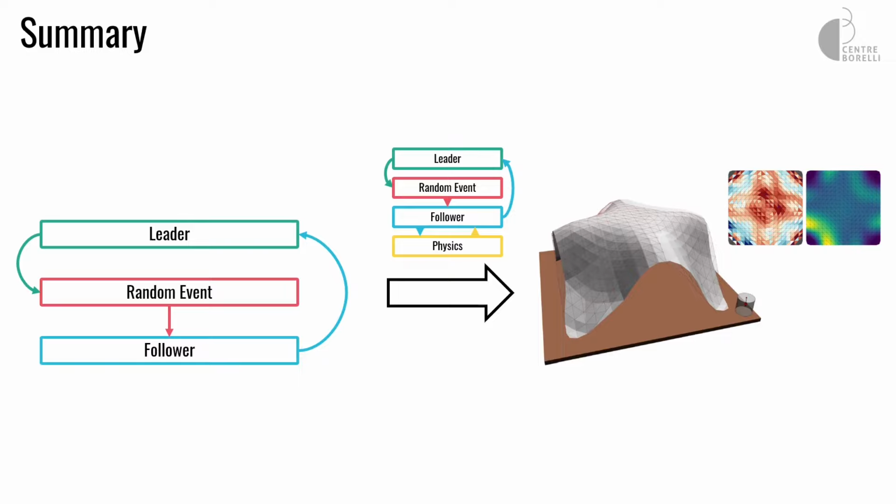Okay, and typically in elastic shape optimization, what is usually done is you fix one load scenario, so you have one set of forces acting, or maybe you have a small set of load scenarios that you predetermine. Like say, I have 10 different load scenarios I want to be robust against, and then you take a solution for all of them, or take the average of solutions and so on.